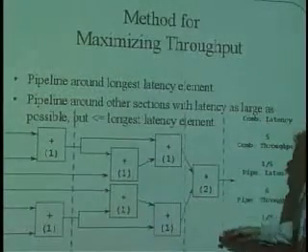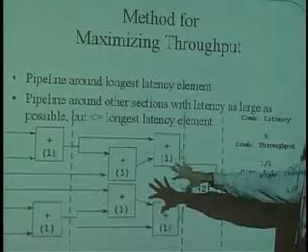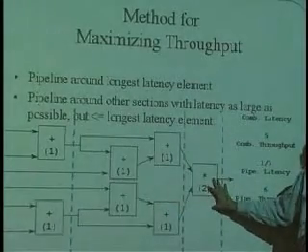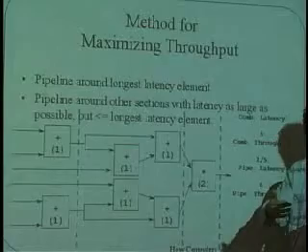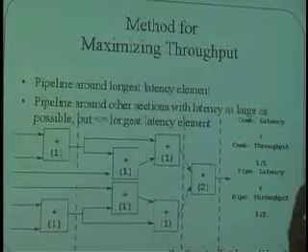And notice, of course, the way that we draw this across all the data paths, which are going from left to right, and thus we ensure equal delay through every data path to every element in the circuit. Okay, there's never going to be a skewing of one piece of data with respect to the other one, if we do it in this case.